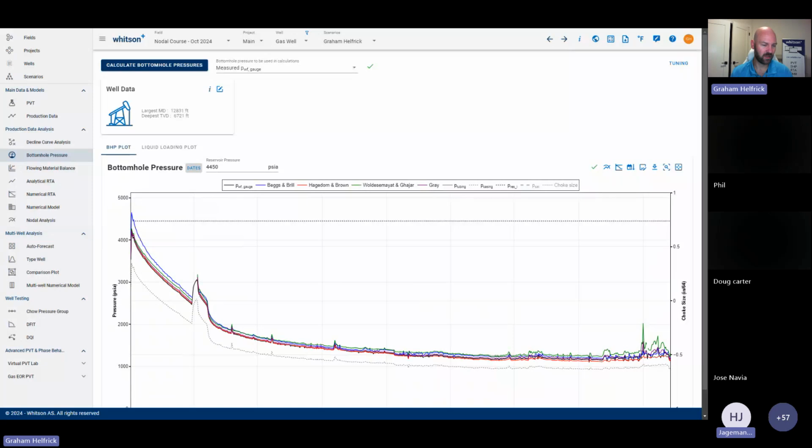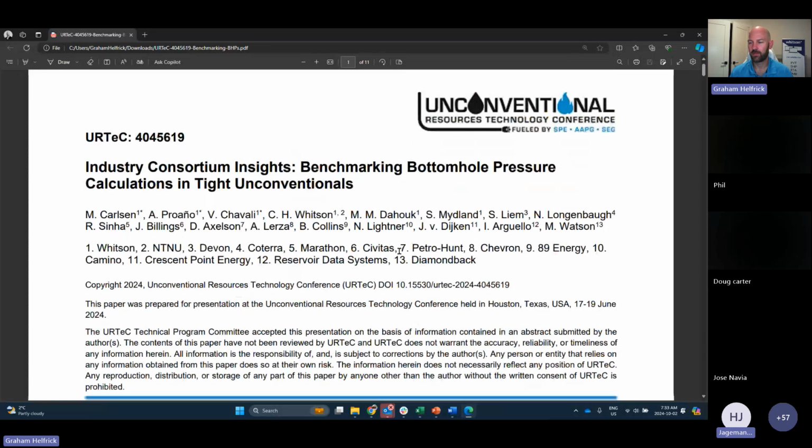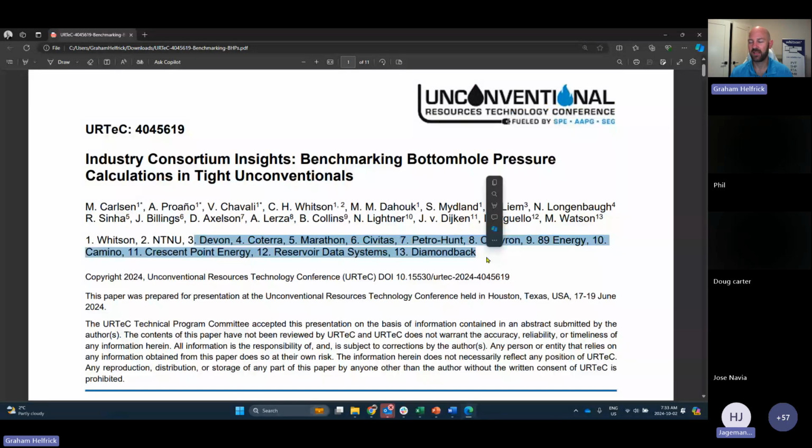And I want to share a quick paper with you guys, and I'll make sure you get a copy of this after as well. We have some great partners, Whitson, and these companies here provided us with, I think it was 600 gauge data sets, downhole gauge data sets with daily downhole pressures. After sifting through them, we narrowed it down to about 400 data sets that we really trusted. So I think over 300,000 data points overall. And the whole purpose was, if we have a measurement of the downhole flowing pressure, let's compare which correlation is the most accurate against the measurement.